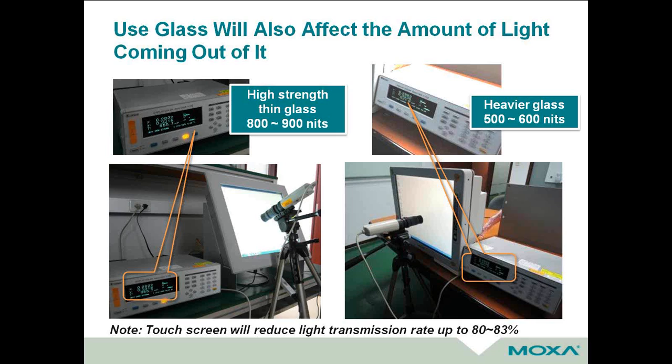So generally, we recommend over 7,000 nits for any panel PC that has a strong requirement of visibility for the operator to control operations. You're going to want that, because when it's all said and done, you're going to lose about 1,000 to 1,200 nits just by having a robust screen and insulation layer under that screen for your panel PC or HMI.